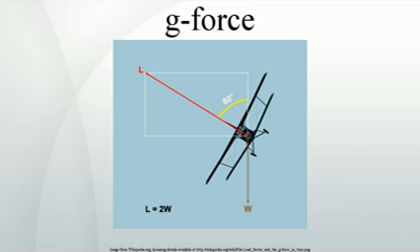G-forces, when multiplied by a mass upon which they act, are associated with a certain type of mechanical force in the correct sense of the term force, and this force produces compressive stress and tensile stress. Such forces result in the operational sensation of weight, but the equation carries a sign change due to the definition of positive weight in the direction downward, so the direction of weight force is opposite to the direction of g-force acceleration. Weight equals minus mass times g-force acceleration.